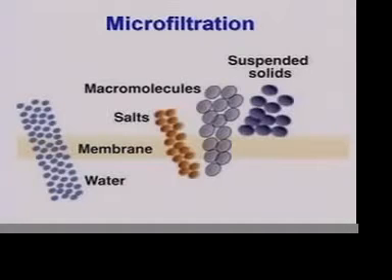And there are 4 basic membrane processes today. Microfiltration: membrologists differentiate between these 4 technologies based on pore size. I would rather use the function to distinguish one from another. The function of microfiltration is the removal of suspended solids.